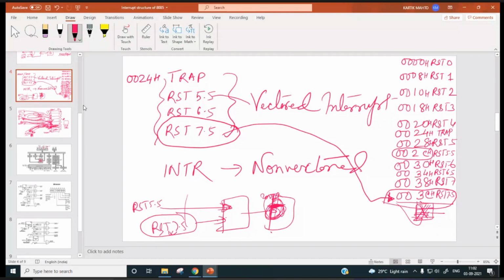Now this turning on and turning off the valve, very easily it can be done simply by outputting 0 at SOD pin. You can turn off a valve, or you can turn on a valve by simply outputting 1 at SOD pin.